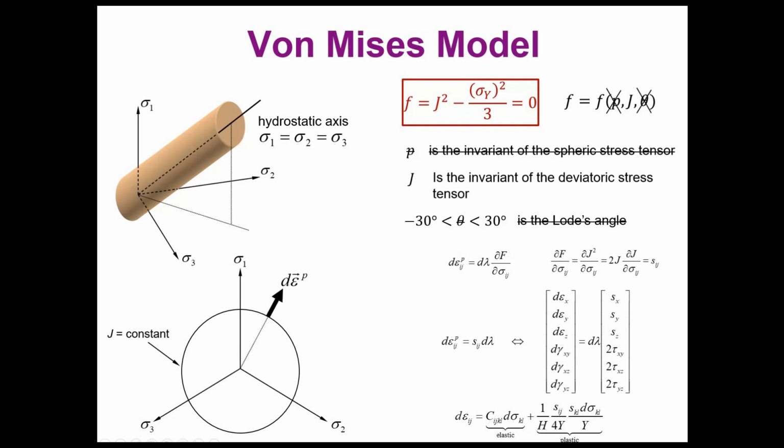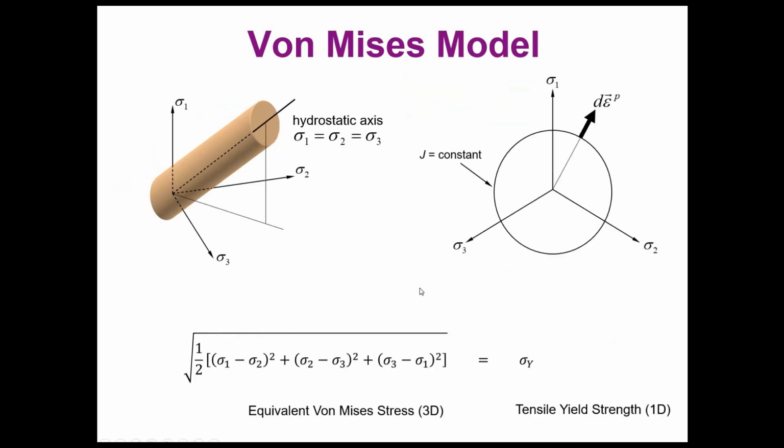So this is the classical von Mises failure theory, that is connected with the plastic theories, because we are using this failure theory as a yield surface in a plastic model to calculate the value and the direction of the plastic deformations. So the failure theory is much more than a failure theory now. It's part of the plastic theory.